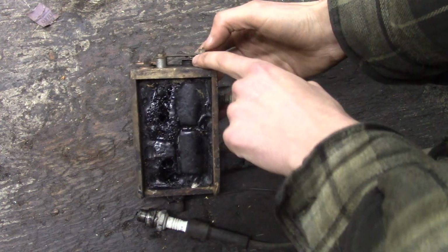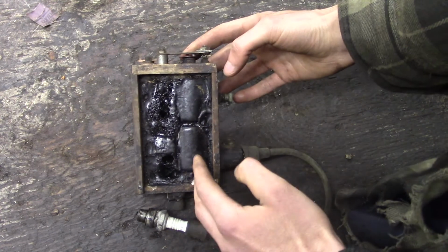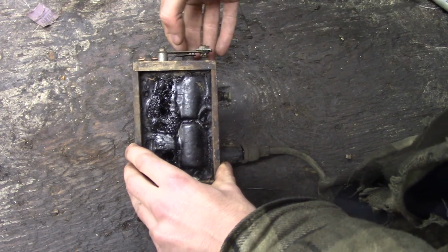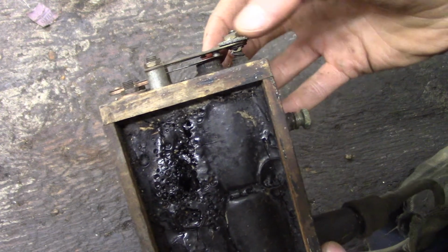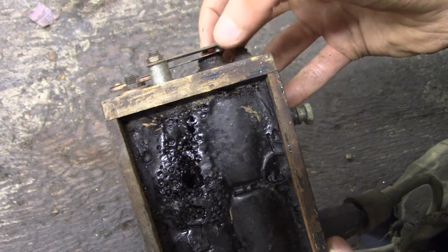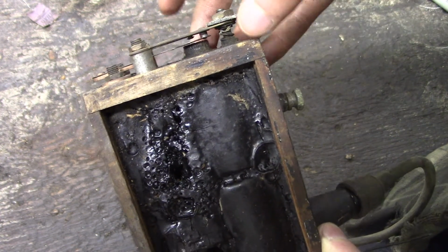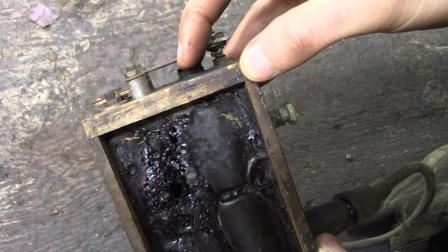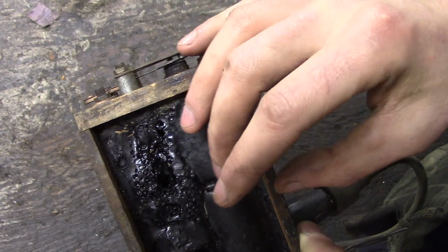when the primary coil is energized with a battery, of course that creates a magnetic field like we discussed, and that pulls these little points away. I don't know if you can see that move, but it pulls the points away, and when it does that, it breaks the primary circuit. So the magnetic field collapses and it makes a spark.